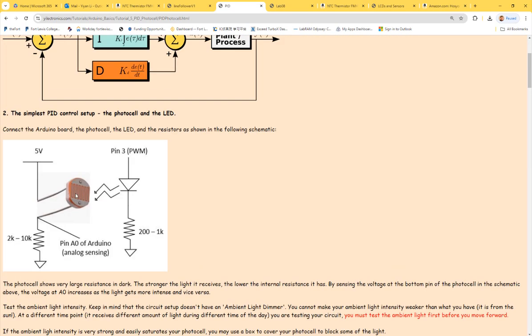Given that this is a light sensor, a photon sensor, it's very simple, it's called an LDR. It's a light-dependent resistor. You get more photons, you place it in a brighter room, it gets lower resistance. If you put it in a dark room, the resistance can be as high as 10 megohms. The resistance decreases very quickly whenever you give it a little bit of light. It almost decreases to 0, only like 30 ohms, if you have something lighting up just next to it.